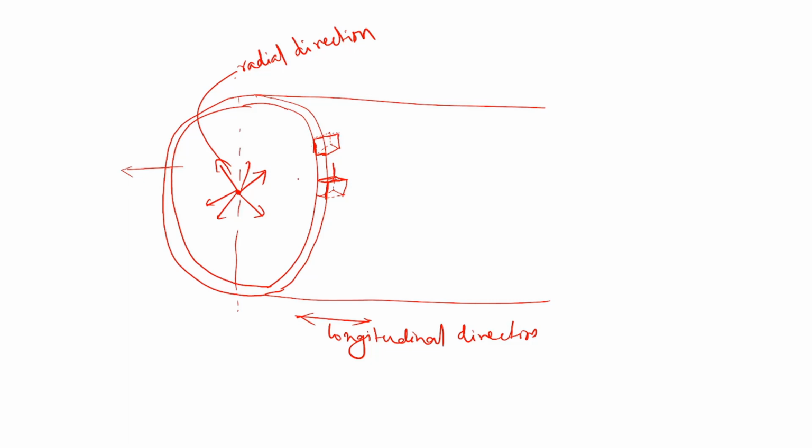Whenever you take a cylinder which is pressurized, the stresses at any point or at any element are all tensile stresses, because it is elongating because of the pressure inside. So if you take this element outside, I'll draw the same element in big size.